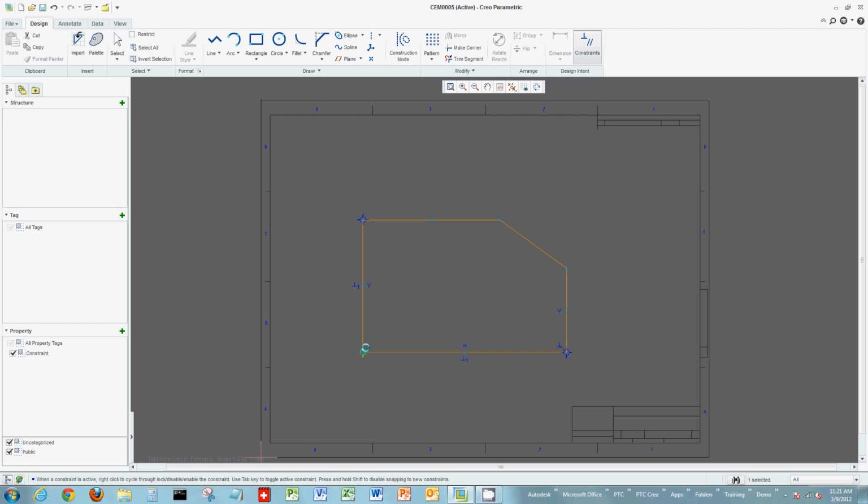You can also choose to change or move things. So if I go to my select mode, and choose to select things or move elements around my screen, I can select a point and start to move that element freely around the screen, but as I move that, I'm going to see it snap to certain constraints: coincident, midpoint, midpoint again, tangent, endpoint, equal length lines, parallel lines, crossing lines. These are all intelligent drawing aids that are going to turn on as you sketch the element around.